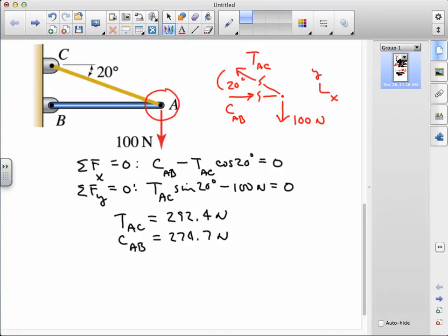Note that the magnitudes of these loads are about 3 times higher than the values obtained in the previous illustration to support the same 100 Newton load. The presence of a shallow angle with the horizontal represents a very inefficient way to react to vertical load. Since every structural element has a failure load, we generally want to minimize the load each element carries when we configure supports to carry a given load. Choosing a cable bar configuration more like the first illustration, where the vertical components of supporting members are larger, is preferable to choosing the much flatter configuration of this example.